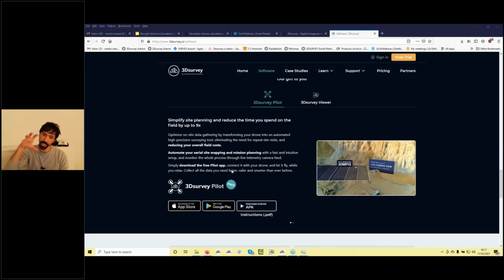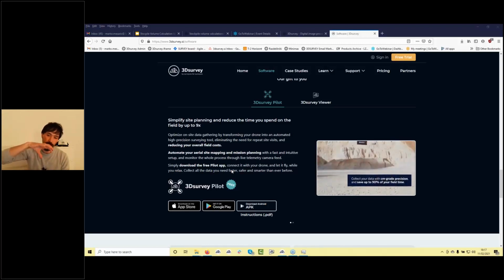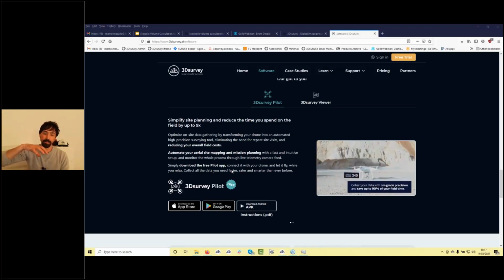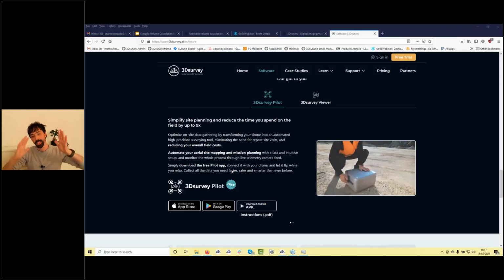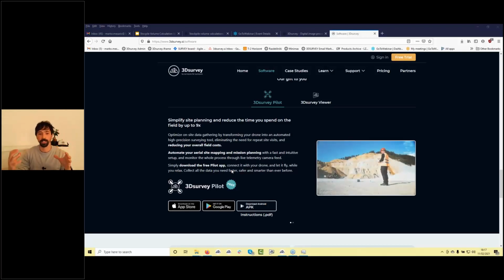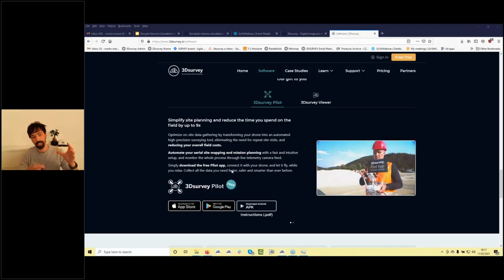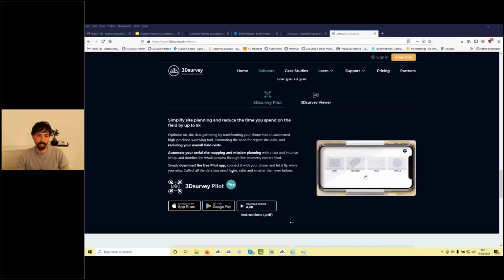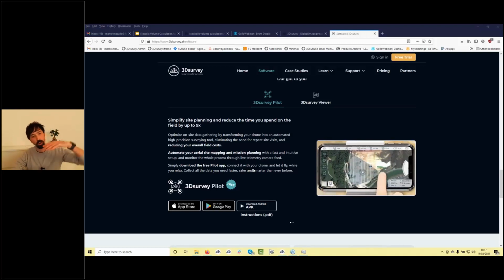You don't need a front view or anything like that. This is more important if you have houses with details under the roof, or a lot of trees and you would like a point cloud near the trees. Just go perpendicular to the ground, single grid flight, and that's it.